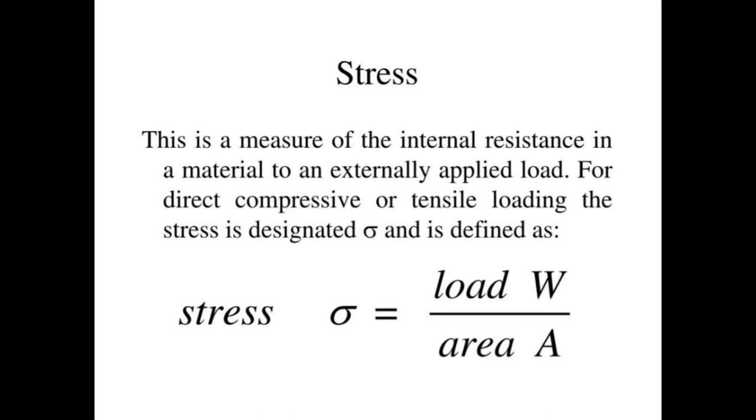Due to external load, the pressure which is created inside the material is stress. For direct compressive or tensile loading, the stress is designated sigma and is defined as W by A, stress which is equal to load by area.